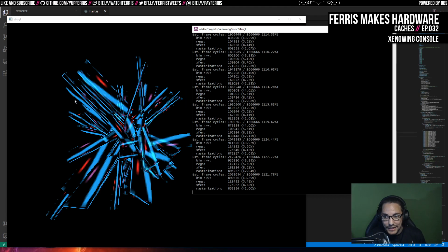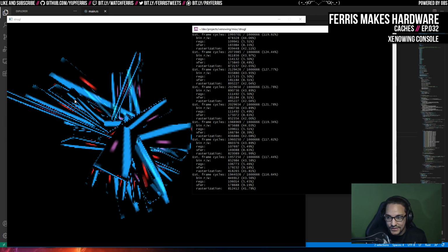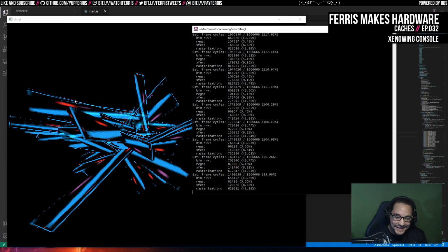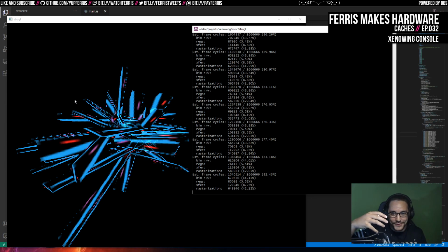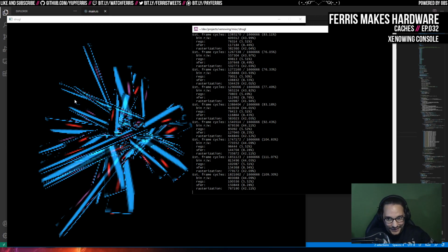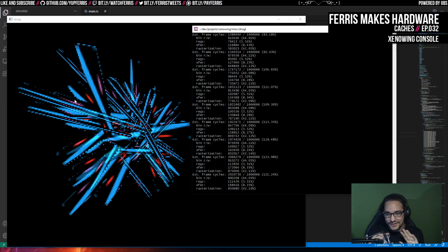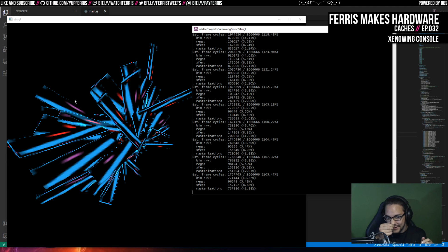So I'm thinking I can make it a lot smaller practically, and support larger texture sizes by doing just a regular cache. That way I should be able to feed more pixel pipes, which will fit well with also having MIP mapping, which will ultimately save bandwidth. Right. So it's all these little related things that are all supported by just changing how the texture cache works. So I'm definitely going to make that decision.